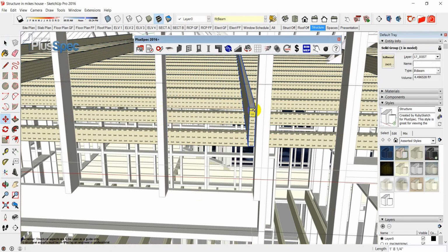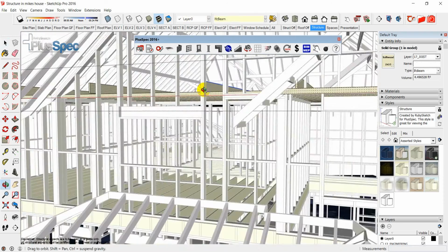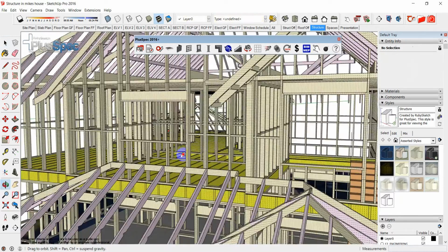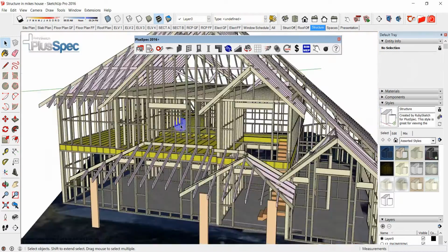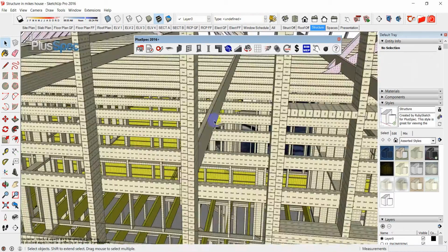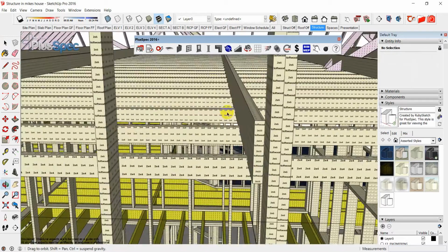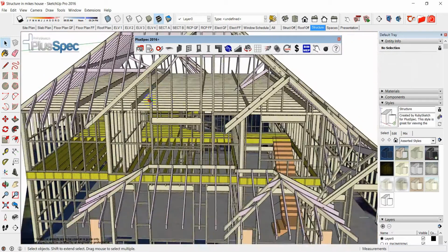looking for my red axis, and therefore I can now follow that load path down. You can see that load path, it's a solid block wall. I believe that would probably be strong enough for what it's holding. This member here is just holding the weight of the center of these ceiling joists.